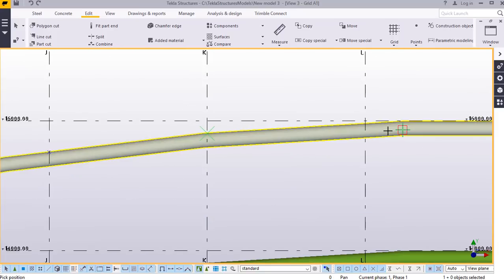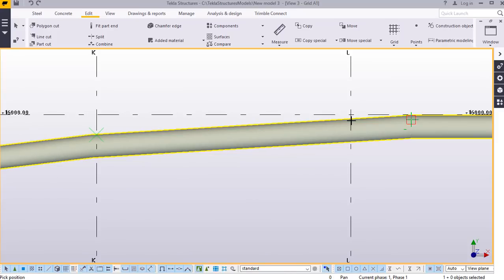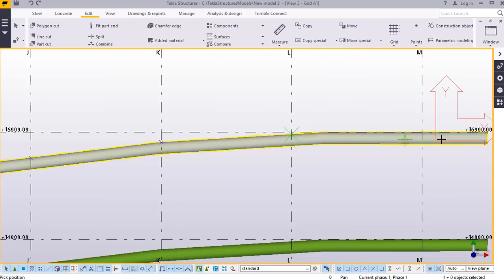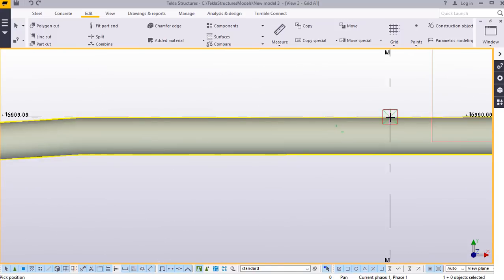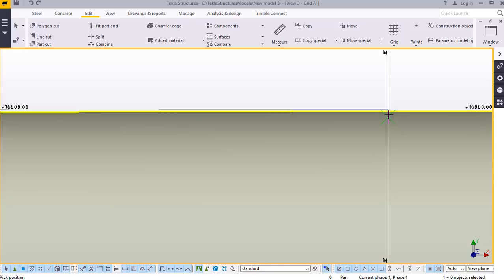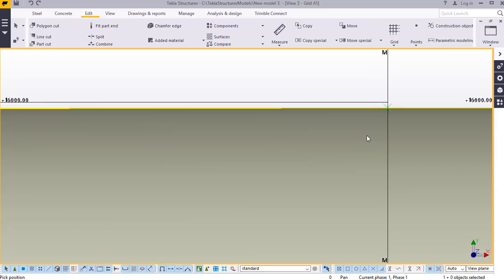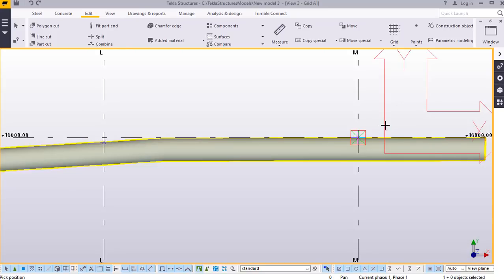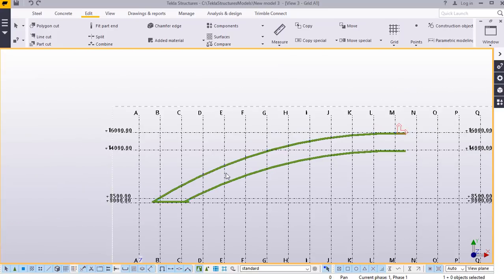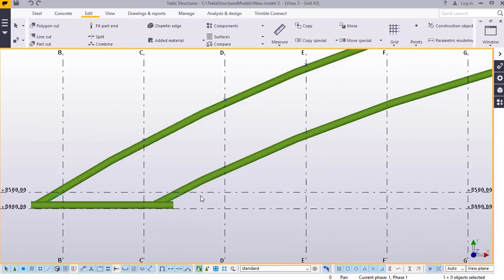This is just to guide us in placing the internal diagonal and vertical steel members to support the top and bottom chord of our truss. Let's place another one here. And zoom closer. Want to place another one right on that position, right there. Then zoom out. After placing that, right click and interrupt to get you out of that points command.